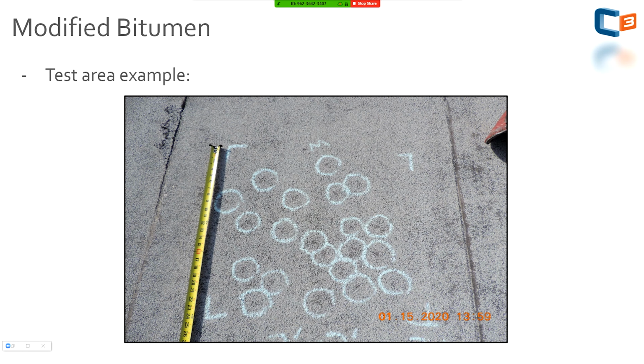And in this 2x2, we'll draw it out. This also, because we cut these roofs, we don't want to cut a 10x10 back. That'd be insane. So we do a smaller test area. We circle areas of granule loss in this case. You can see the M in that test area, and I'm identifying mechanical damage. So this was obviously a mechanical mark. It wasn't circular. There was no bruising. And the granule loss was obviously caused by a mechanical mark.